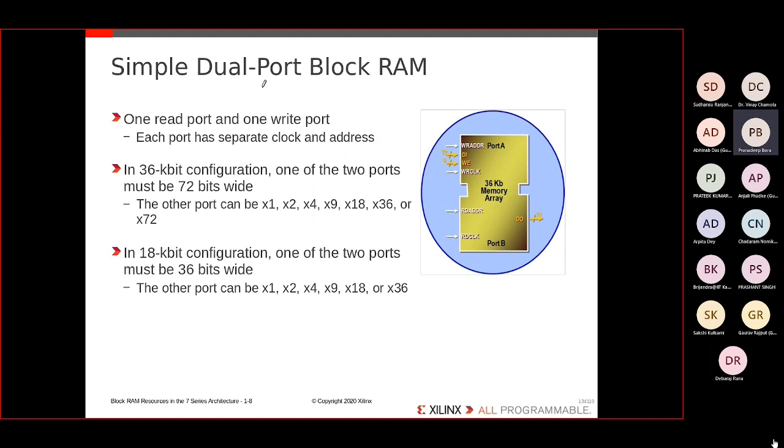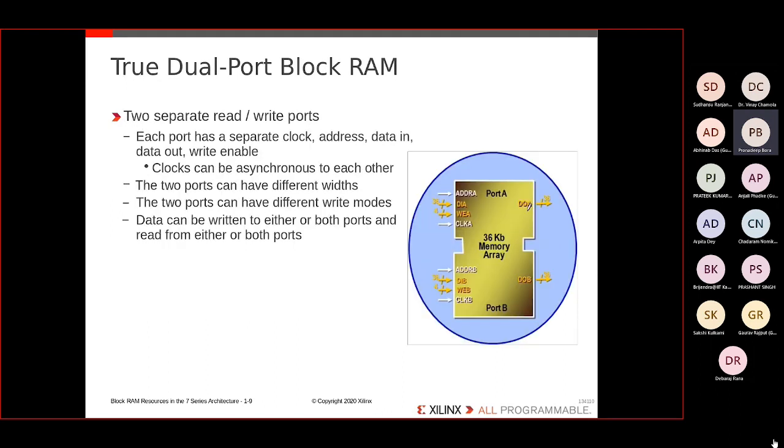Similarly, we have simple dual port. These are the three configurations I can use. This port is for write, this port is for read. Simple dual port separates it. The most important thing that we'll be regularly using is this true dual port RAM.